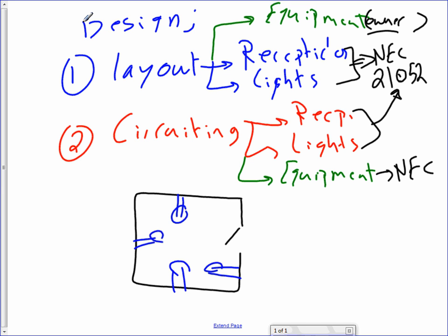Now, some of you would say, Chad, where's the center of this wall? There's a door. Pick a location. If you have a receptacle, would you put it behind the door or here? Typically here, because you don't want the door to close over it. So that's the concept of receptacle layout without knowing anything.